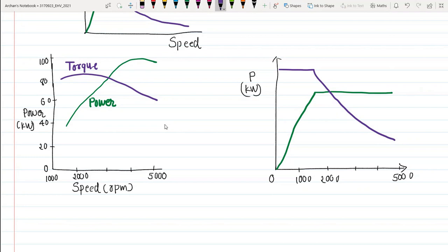So now we talk about this IC engine. The internal combustion engine usually has torque speed characteristics which are far from the ideal performance characteristics required by the traction. It starts operating smoothly at idle speed, right? Good combustion quality and maximum engine torque are reached at an intermediate engine speed, you can see.